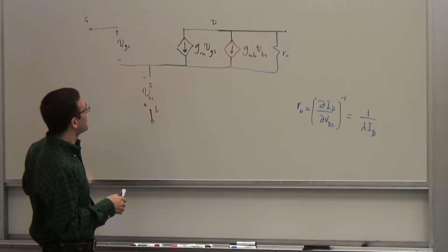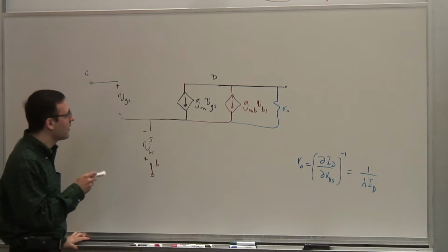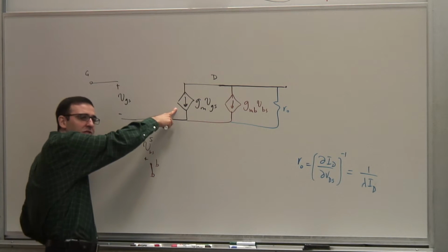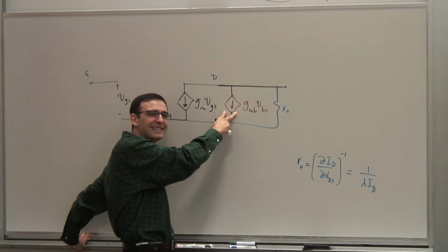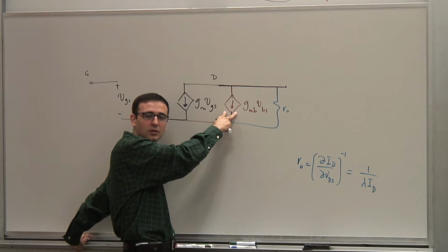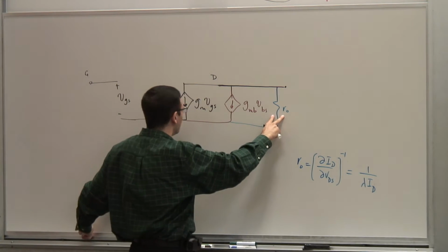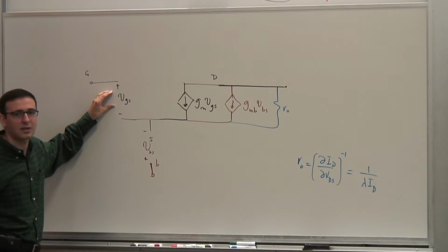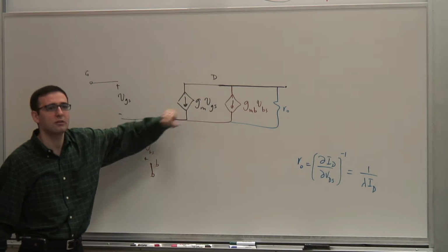Now let's come back to our transistor and see what we have so far. So far, we have this GM, the transconductance of the MOSFET. We have the transconductance of this back gate transistor, sometimes that's what it's called, or the bulk transistor, GMB. And then we have the RO. And we saw that the resistance here, unless your gate oxide is very thin, is not significant. So this was the basic low frequency model.